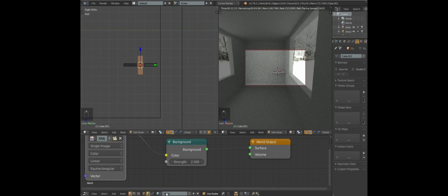Well, I know in my luck I may have to go tell it I have these. So if you want to see if you have the GPU compute, while it's loading the cycle, we can look at this. Go to the file menu, user preferences, system tab, and you will have something down here if you have a 3D card. Those can help speed up the render time. So if you have these, definitely use them. It will be to your advantage.